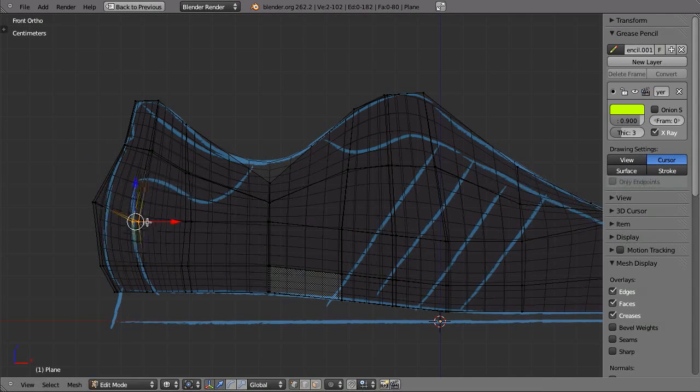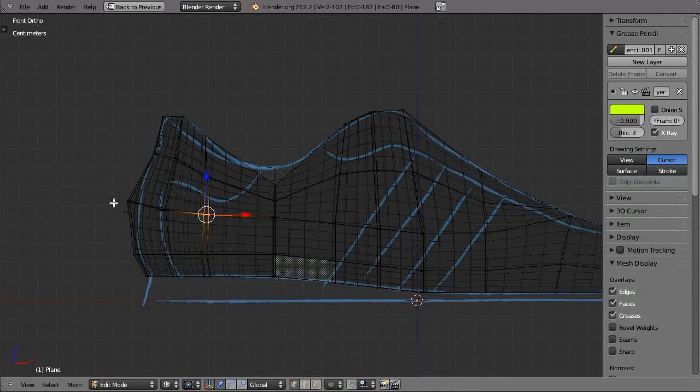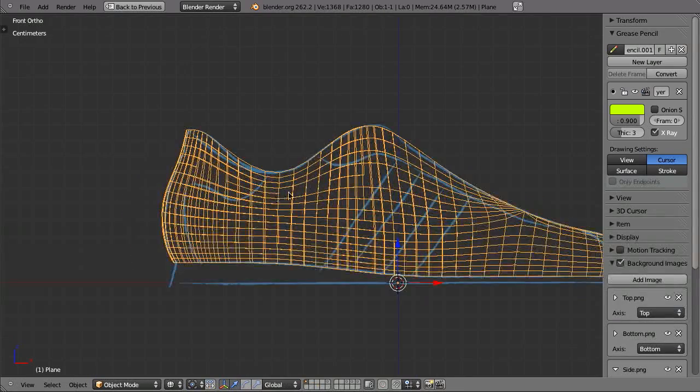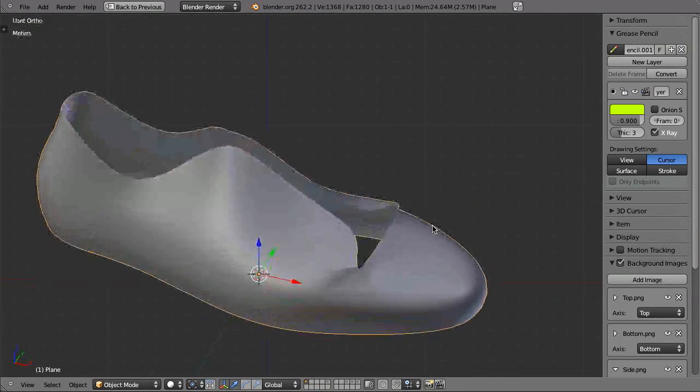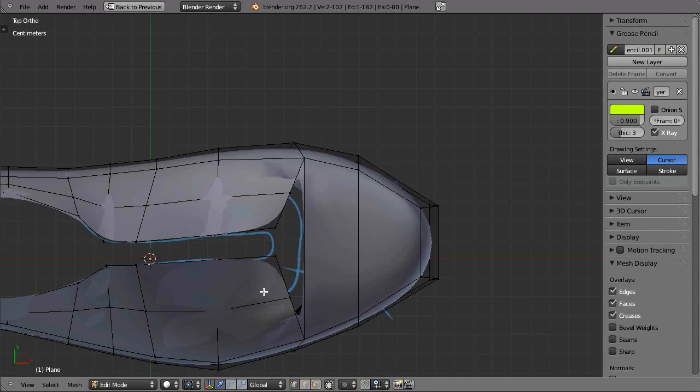And as you see, quite often when you add details, as I said, it can quickly turn into readjusting your vertices, because when you work with the subdivision modifier, every time you add a loop cut, your curvature changes.